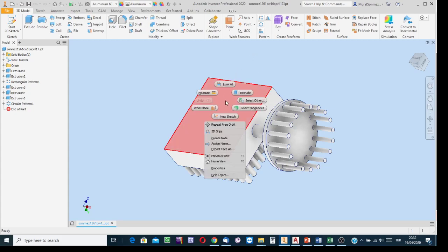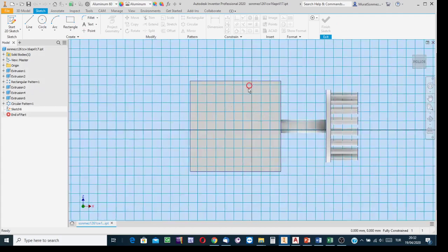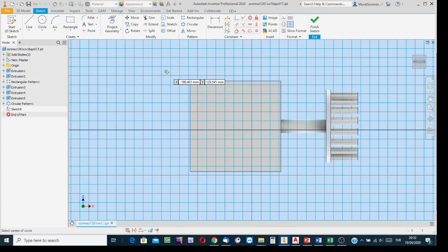Take a sketch right over this surface, a new sketch. Okay, and then create a circle. In this example, again, the members of the family are just cylindrical extensions. So create it as a base arbitrarily. And then locate this one, since it is the base of one of the members of the family, and the family is a circular distribution, using the radial coordinate.